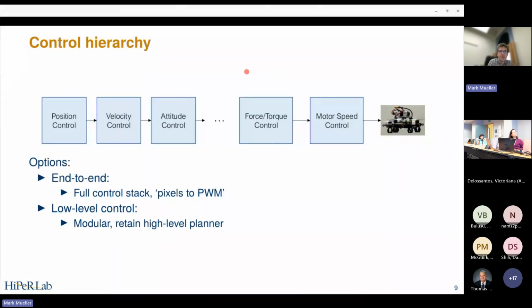But the physics enters very strongly in the lower levels, where your controller generates angular accelerations and those get transformed to torques by an estimate of inertia, etc. So we will replace the low-level control with our learned controller, the part where the physics is really relevant, and leave the high-level control generic.